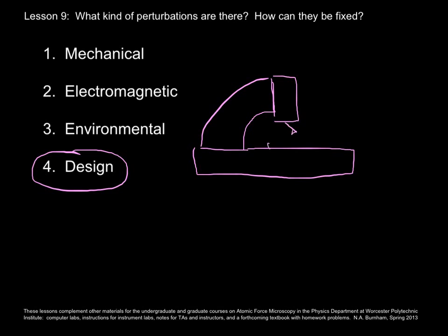The reason why it's done this way is because now we can have a motorized stage down here with an 8-inch silicon wafer there. That motorized stage allows you to go to several places on that silicon wafer and check for roughness.